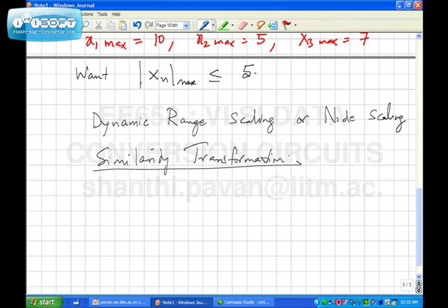Eigenvalues are preserved because the closed loop poles are the same, so the eigenvalues must be the same. In other words, the original system was of the form x dot is Ax plus Bu, y is Cx plus Du. In a delta sigma modulator, the loop filter D must be 0 if there is no excess delay, because D is the direct path from the input to the output. If you have excess delay, you will have a direct path to compensate for it. But this is the nature of the equations.